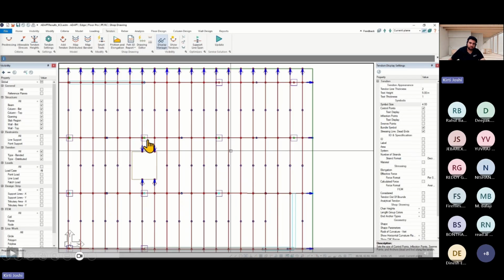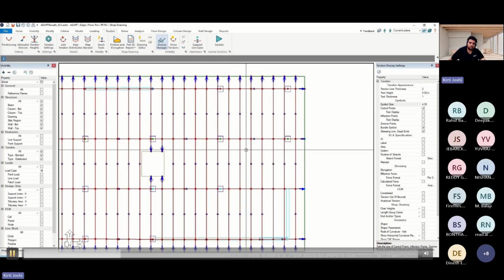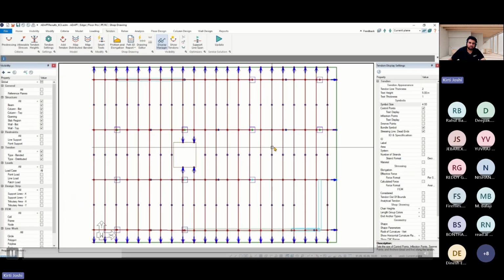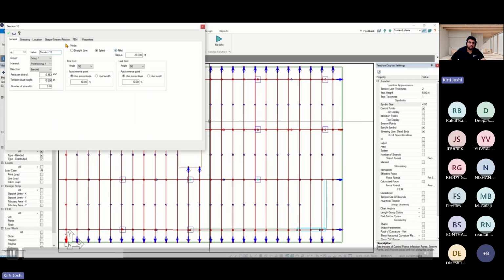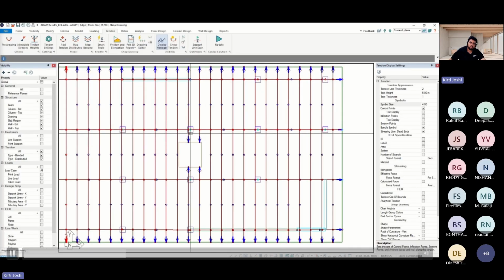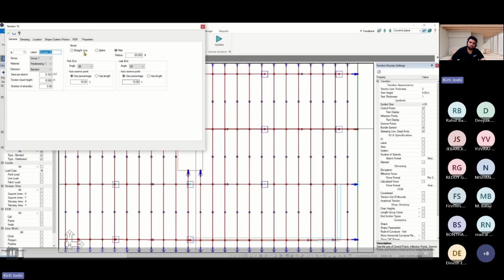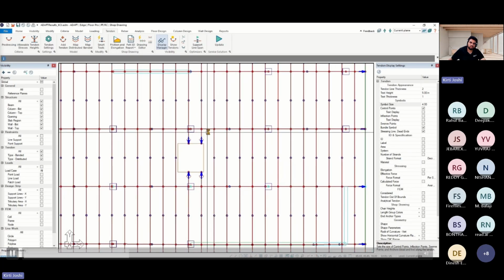So again, I mean to say that when I have changed the tendons from linear to fillet, then the color has been changed to green. You can again select each of the tendons, and once you click on the fillet, its color will again be changed. Based on the tendons, its high point and end point will be changed. You can also change that as well.